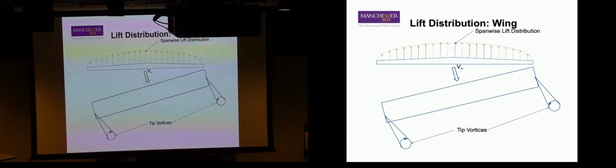It must either equalize via flow, i.e. those tip vortices, or you must get a shock wave. Again, to get a shock wave, the flow has to be traveling faster than the speed of sound. The flow above and below the wing tip, external, is not relative to each other faster than the speed of sound. It has to go to 0.